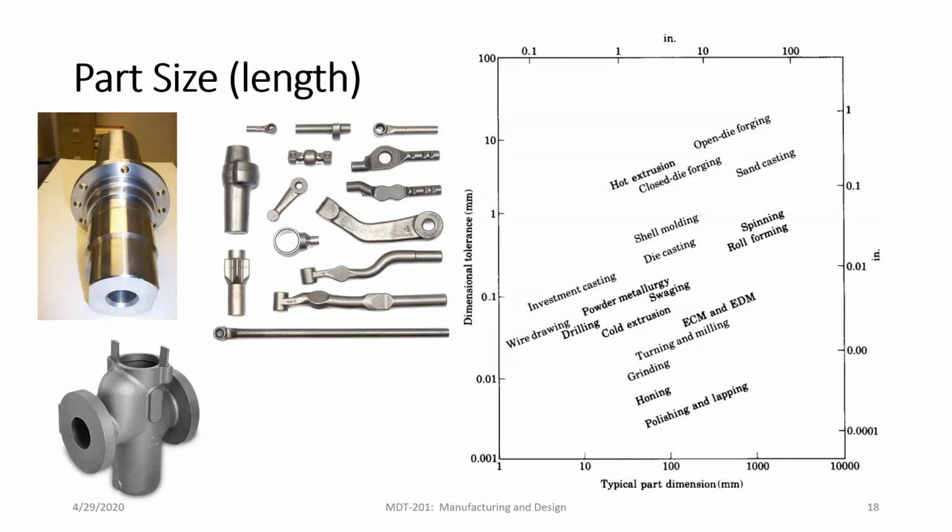That's another cost factor. Do you have secondary or tertiary manufacturing processes that are necessary? Most of these, especially the open die forging and the sand casting, which cater to large dimension parts, are going to require secondary operations. So there's a cost factor right there.